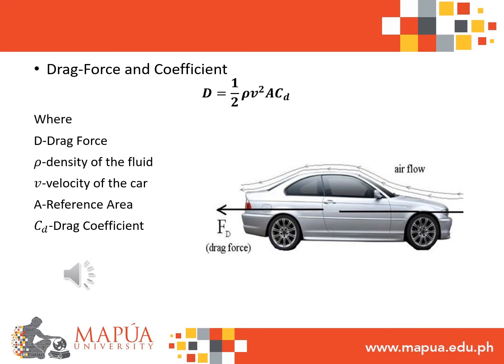Another important parameter to consider when designing the external body of the vehicle is the reference area. When the reference area of the vehicle is large, the drag force that will be induced will also be large, and if the reference area is small, then the drag force will be less. The density of the surrounding fluid also affects the drag force. The denser the fluid is, the higher the drag force that can be induced.